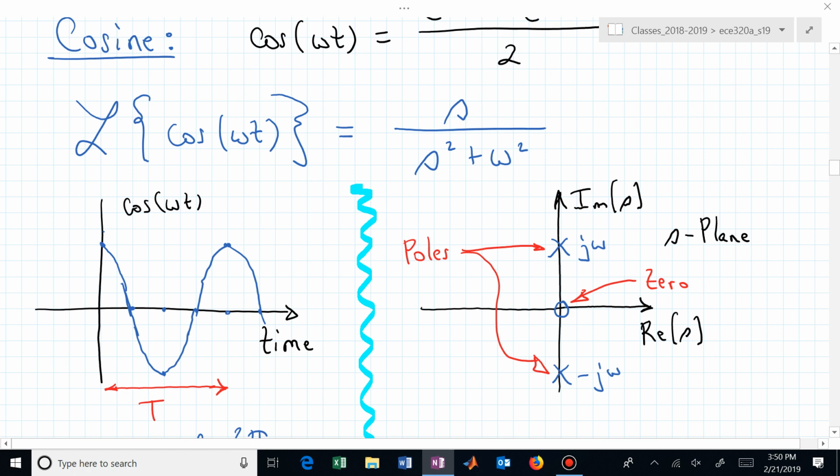This is chapter 9, isn't it? This is sinusoidal steady state. So you've reached now a steady state. It's not decaying. You're now hitting a system with something that's at this particular frequency, omega, for all time. And now it's caused every element in your circuit to be oscillating at that omega. They may be shifted in time relative to the input, but everything in that circuit, since it's a linear circuit, is oscillating at that frequency omega.